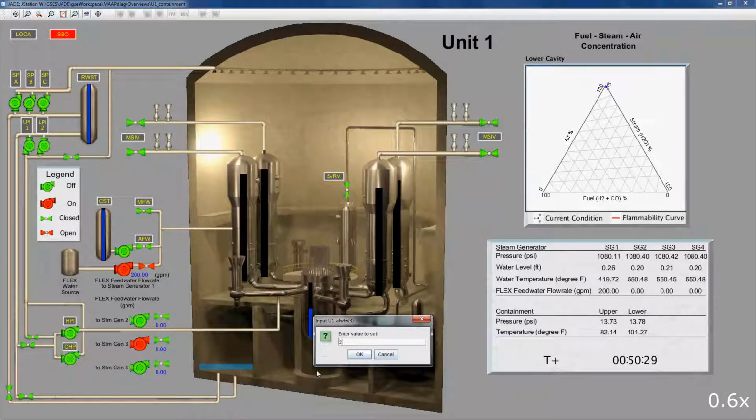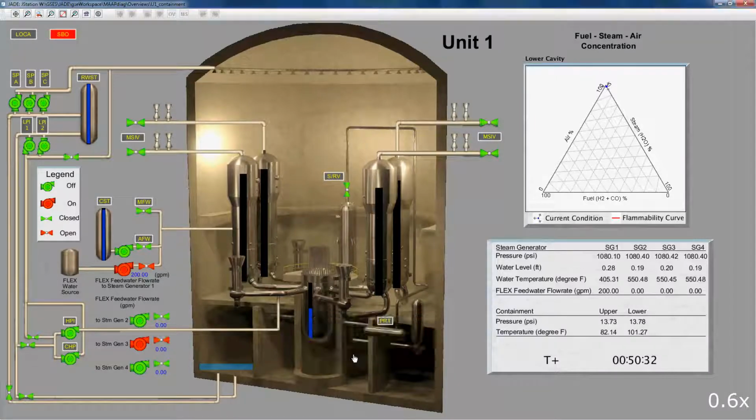It is not shown in this video, but the power of the DesignEP platform is the ability to interact with the event. You can stop or pause the event, and you can go back in time to change parameters and watch the results. For instance, what happens if the flow rate is changed or the flex equipment is started earlier or later in the event? Data on key parameters can also be trended, saved, and exported for further analysis.